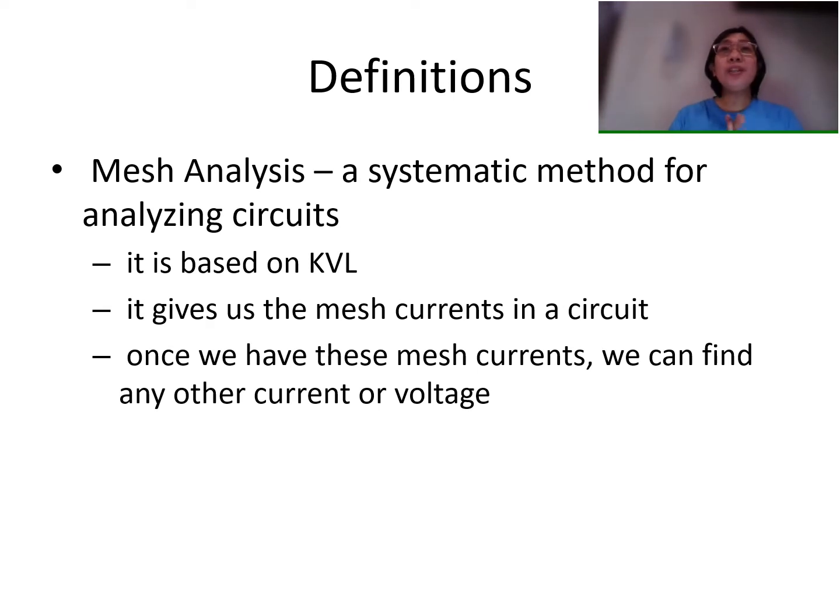Mesh analysis is a systematic method of analyzing circuits. I have mentioned Kirchhoff's laws a while ago. Mesh analysis is based on Kirchhoff's voltage law. It gives us what we call the mesh currents in the circuit. So when we use mesh analysis, we are solving for the mesh currents in our circuit. Once we have these mesh currents, we can find any other currents or voltages in our specific circuit.